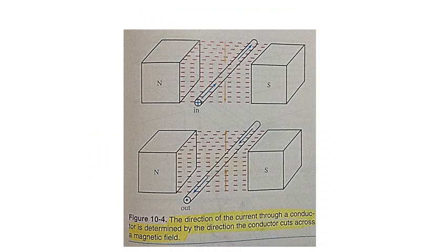How is this induced voltage created? Figure 10-4 shows single conductors passing through a magnetic field. At the top, the conductor is pushed downward through the magnetic field. On the bottom, the conductor is pushed back upward. The current generated is shown by the arrows. In each case, the induced current in the conductor forms a magnetic field around the conductor. The field around the conductor opposes and is repelled by the fixed field.